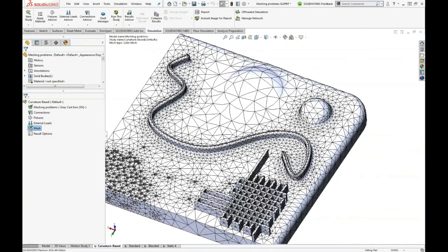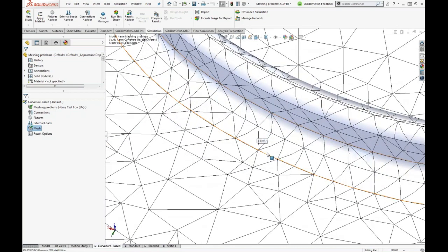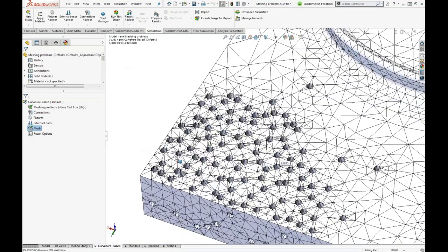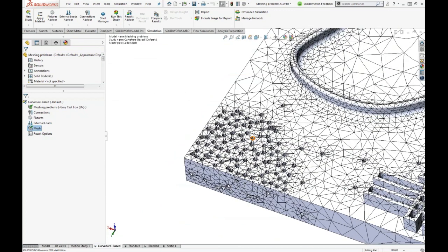And while we're here, we'll just wrap up. Two more questions. Good question from Tom: what is a good rule of thumb for element size versus feature size? In general, there are all these FEA rules of thumb, like two elements across a fillet. But it all comes down to this: you don't sweat it if there's no stress in that area. We'll talk about convergence in a bit, which will ultimately prove out those rules of thumb, and you can start applying that technique.